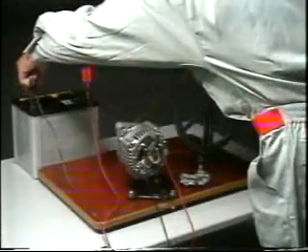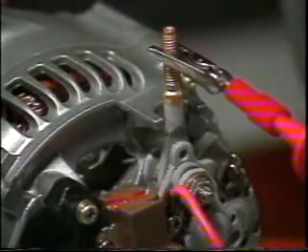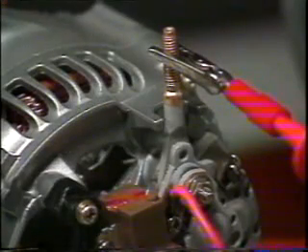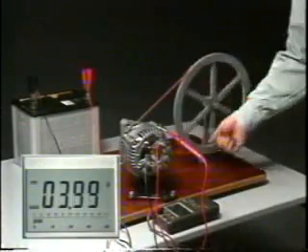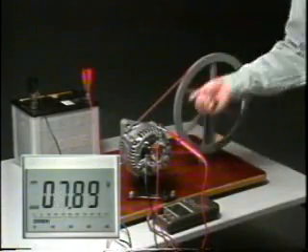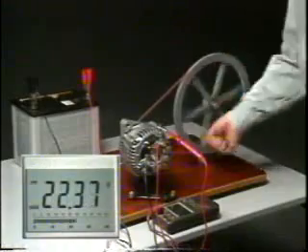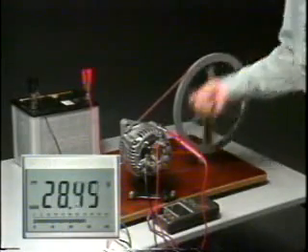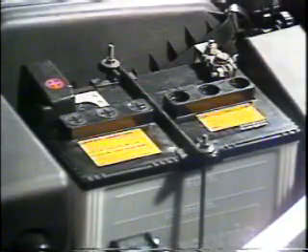First, battery voltage is applied to the rotor coil of the alternator. Then the alternator rotation speed is gradually increased. Let's measure the voltage generated at terminal B, which is the alternator output terminal. As you can see, the voltage increases steadily. If this continues, the electrical components will be damaged and the battery will be overcharged.